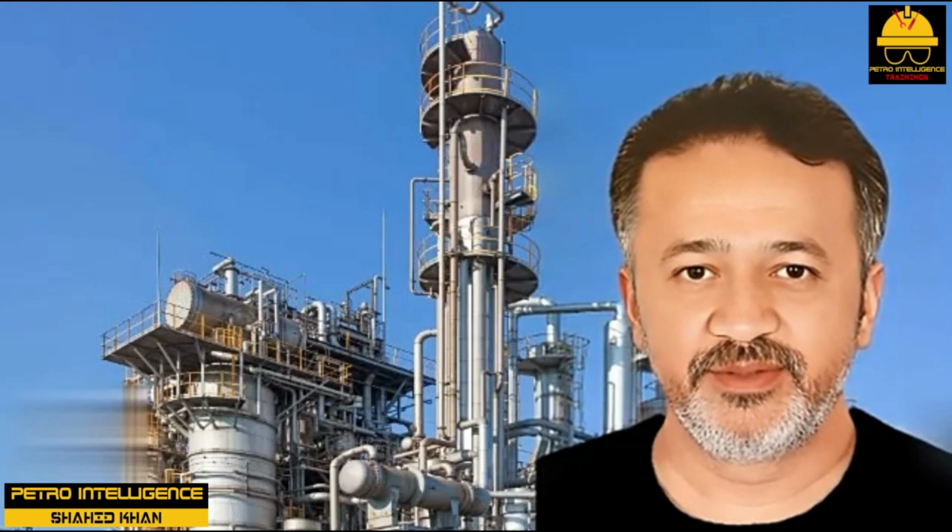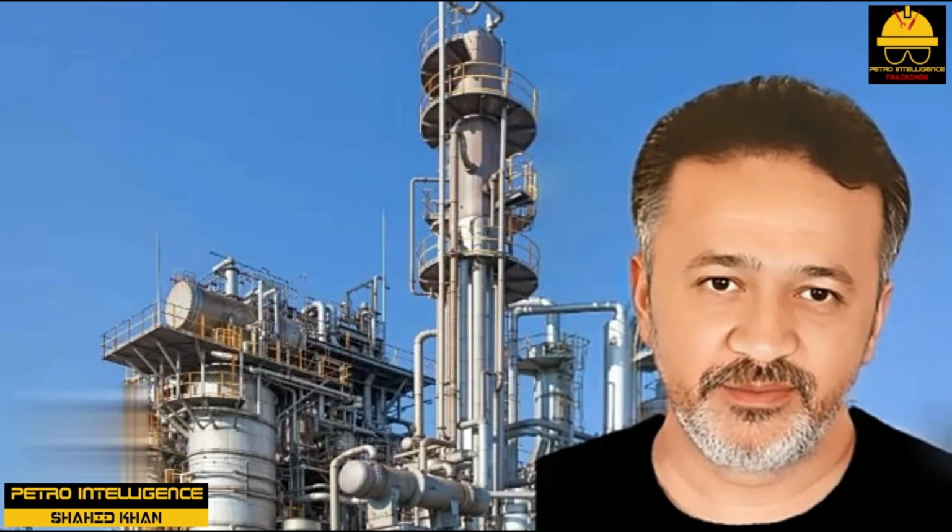Optimizing feed preheater duty. Trays suffer from lost tray efficiency as a result of both flooding and dumping. Trays have some entrained droplets of liquid lifted by the flowing vapors to the trays above. This tends to blow butane up into the lighter propane product. Perforated trays always have some leakage of liquid through the tray deck to the trays below. This tends to drip propane down into the heavier butane product. When we increase feed preheat and the reboiler duty is automatically reduced, dumping increases, but entrainment decreases.